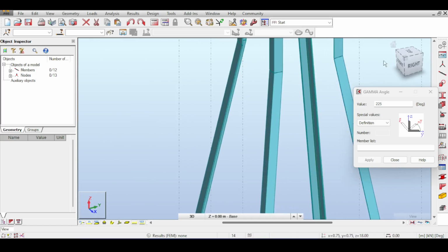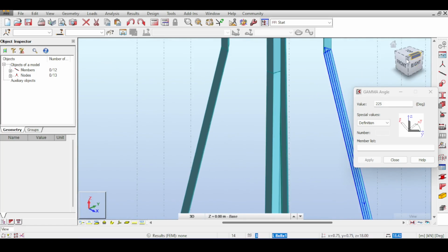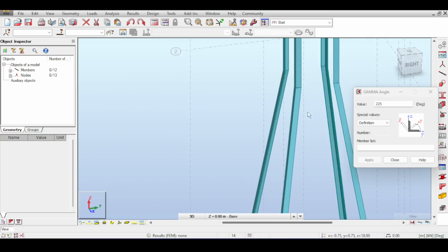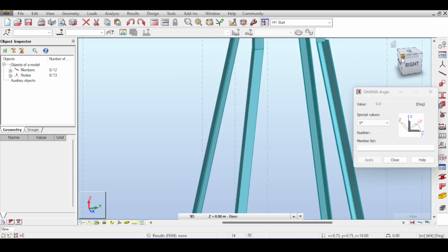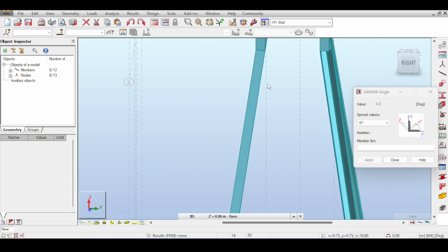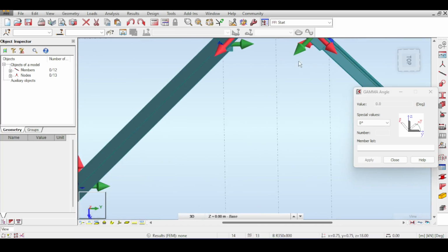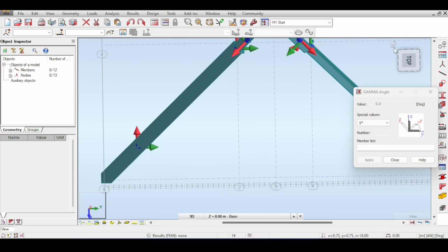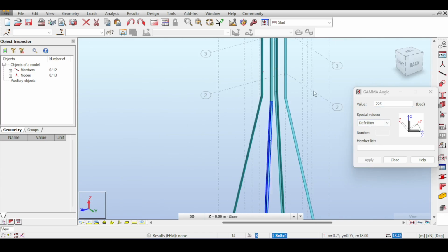Also, those sections having this shape makes it easy to connect the diagonals and all kinds of horizontal members, because you have a leg that you can gusset plate into. Whereas if you had the beginning like this, 0, where can you plate it? Think about it. You want to make a horizontal member and you have an incline on it. So how can you connect a horizontal member to this? This doesn't make any sense. Maybe you need to replay this multiple times to understand what I'm trying to say.